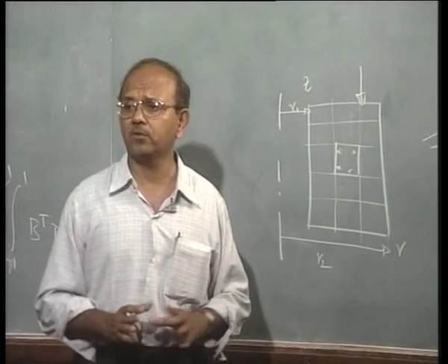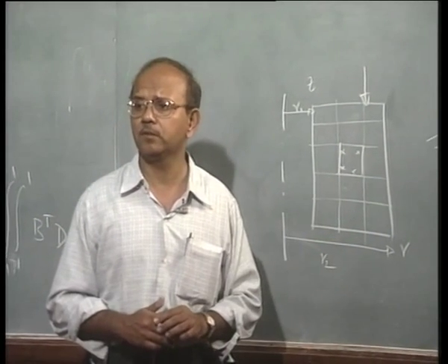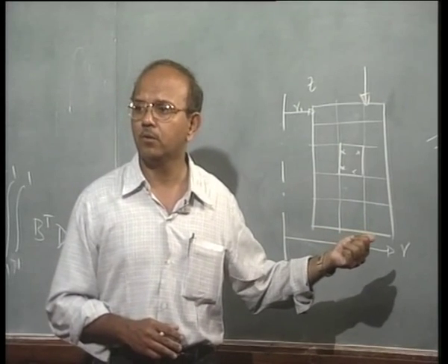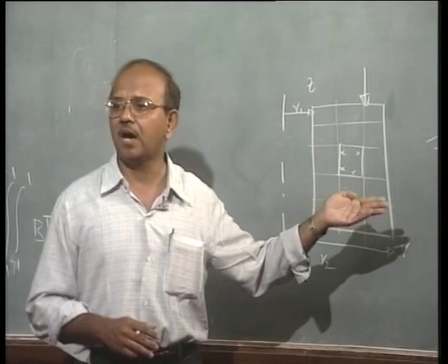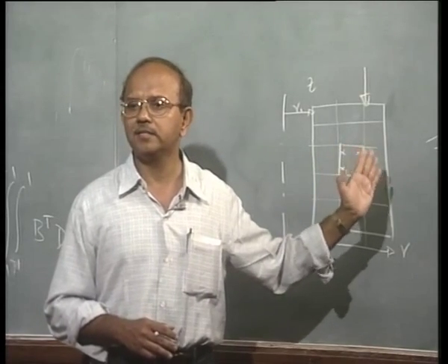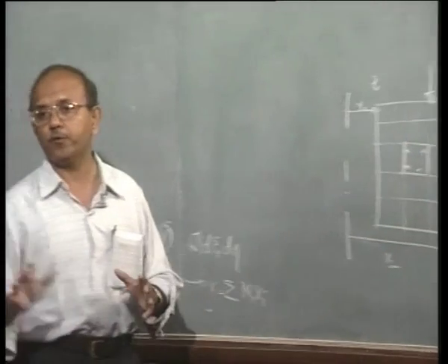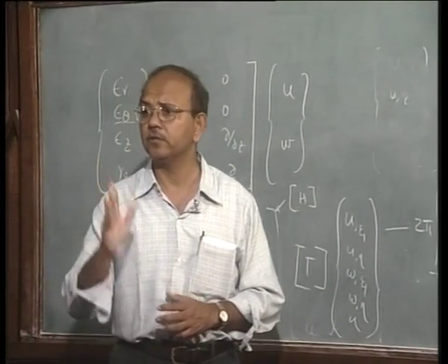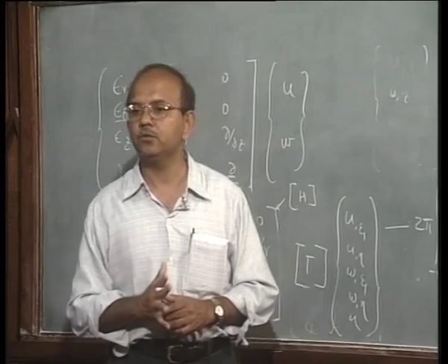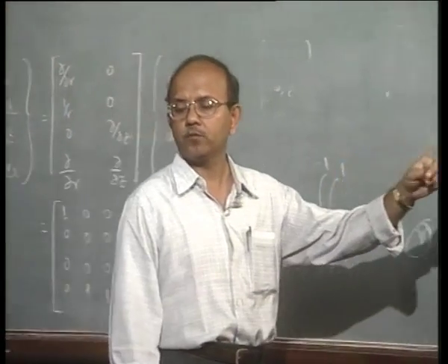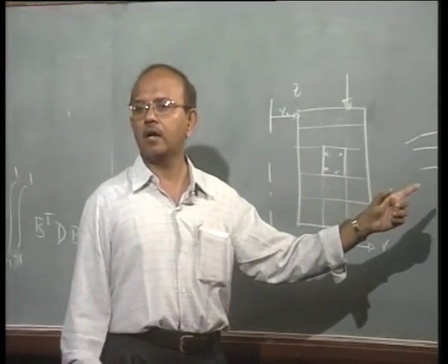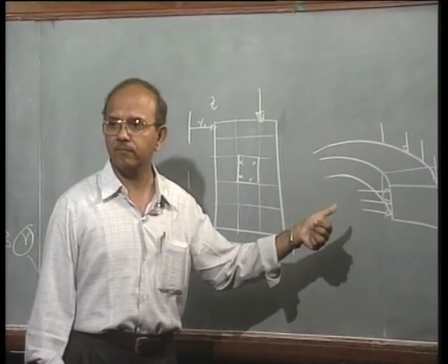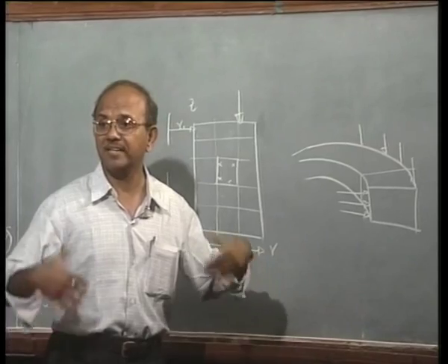The other thing that you have to be careful about in an axisymmetric element is the RZ coordinate system. Okay. Usually the x is r and the y is z. Okay. The softwares usually define this as to which is r and which is z. Okay. You can't go against it. Then the problem is an entirely different problem,